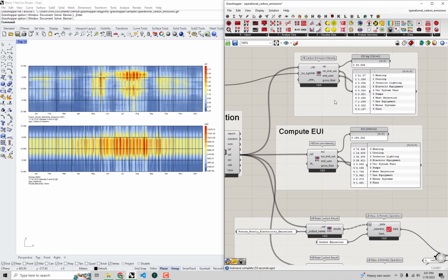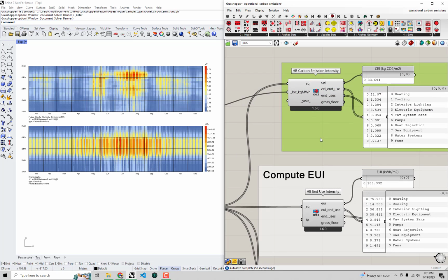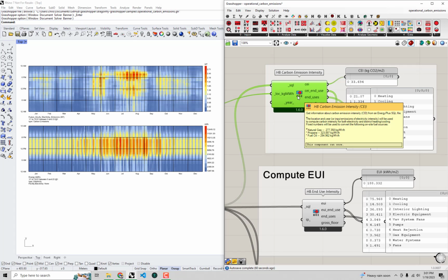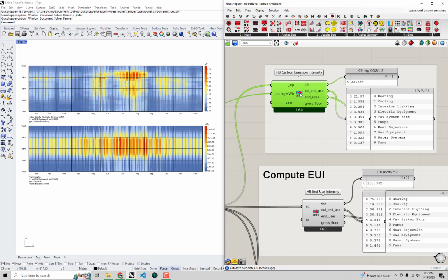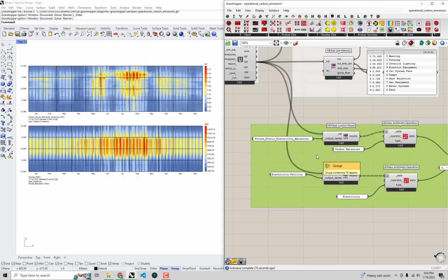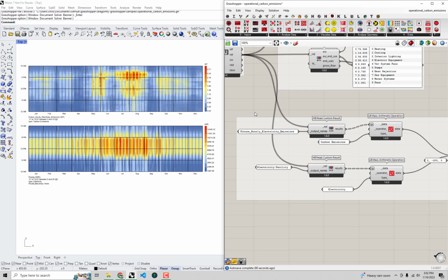But honestly, if I'm really telling you the truth, for most design decisions you can make, this average carbon intensity being used here is good enough for comparisons. And so I would trust this. I would still use this for most of my studies if I were to, let's say, try and give a client an example of what their carbon intensity would be under different situations. This is really good enough, the average here. And this was more just to show you that if you really want to do due diligence and do a production level type of simulation, it is possible. There are hourly values of carbon intensity that you may be able to find for your location.